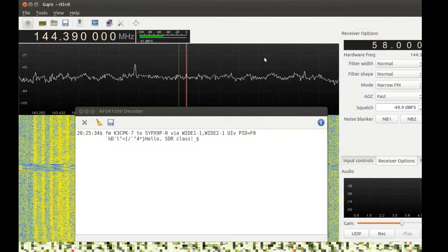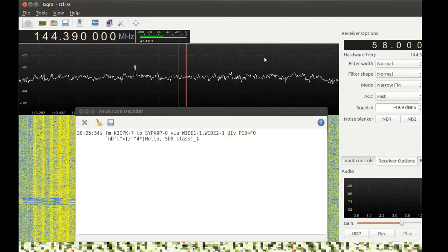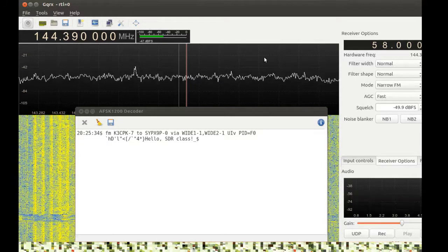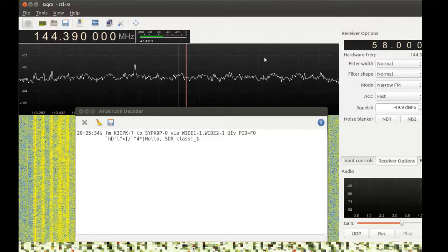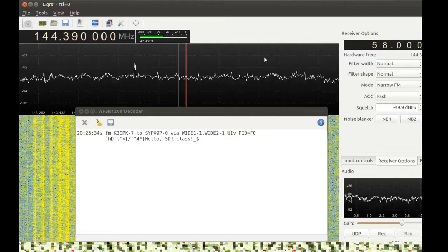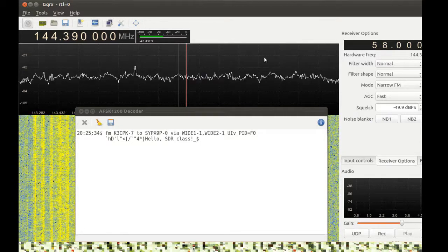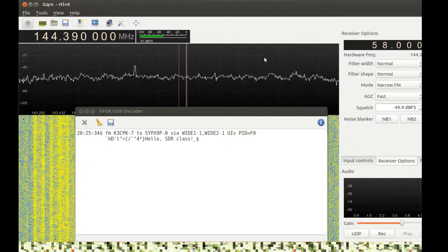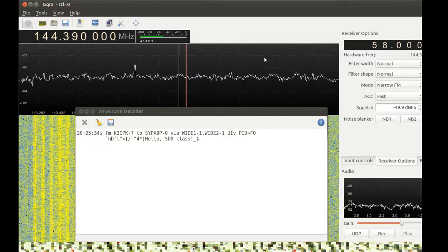So something, but I'm not getting anything into the decoder. Yeah, make sure you're right on 144.390. 144.388 is what it showed up as for me. And your PPM is wrong. I don't know, at the start of the session, I smashed it. Could be wandering. RTLs are known to wander. Oh yeah, definitely. As they heat up, they do wander a little bit.